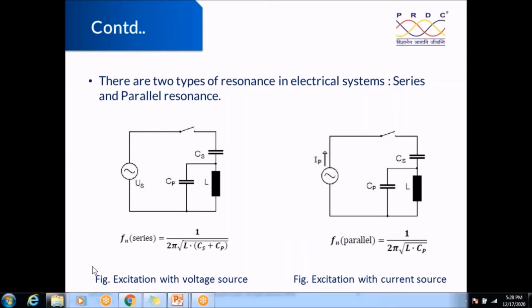Not compared to HVDC, but in HVAC also we have some long lines at EHV level, like 400 kV or 765 kV, around 300 kilometers, or maybe up to 400 kilometers or more. In HVAC transmission lines, in order to limit the steady state overvoltages, we use shunt reactors or line reactors connected to the line.